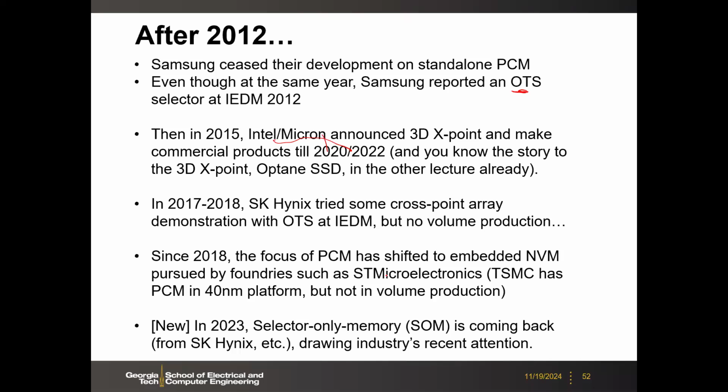So maybe compared to RRAM, the phase change memory's cost is still a little bit higher because the material is a little bit weird, right? Compared to the hafnium oxide RRAM, the power consumption may also be a little bit larger. If the market is similar, right, the embedded non-volatile memory for the automotive microcontroller, then if TSMC has RRAM already in production, maybe they don't want to invest more in the phase change. But at the beginning, like back in 2018, even earlier than that, TSMC had both, okay, on their table, RRAM and phase change.